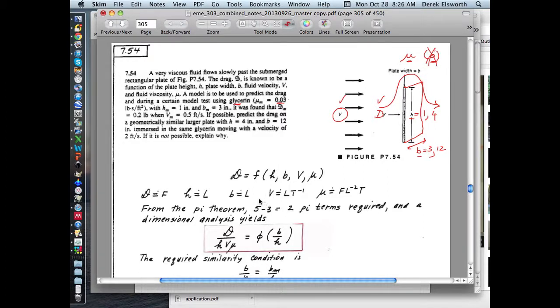And so you have 5 parameters: a drag force, flow velocity, viscosity of the fluid, and 2 geometric parameters. If you go through the dimensions of these, force, length, I never use force, length, and time, I use mass, length, and time. But you see that force, length, and time are all represented. So the number of pi groups, I think we used k minus n, right? K are the number of parameters, 1, 2, 3, 4, 5. Number of groups, force, length, and time are represented.